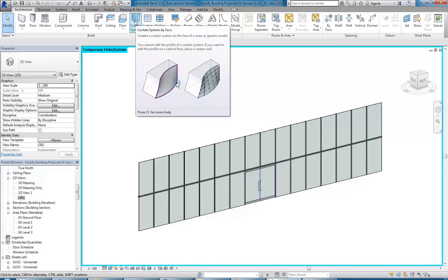So that's using the massing tools. And so before you go too far with that, I'd spend a bit of time learning that mass modelling set of tools that I've been showing you earlier. And at first you'll think, well, massing's good only for those concept models I've been showing you. But then once you go further with assemblies, you can see that you can actually do a lot more with those tools. Again, using all the different options for assemblies that are mostly set up for things like curtain walls. But it gets pretty technical once you get into the setup. You've got to work with parameters and do those other things as well, but also then with massing.